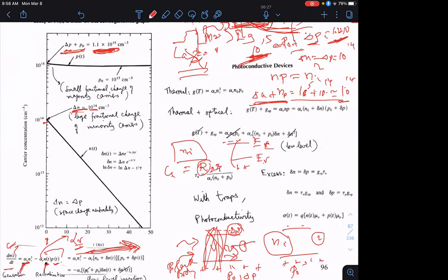It's an unstable scenario. So subsequently, these electrons fall into the hole state, re-emit photons. You absorb more photons, you create more electron hole pairs, they recombine, emit photons, and it's a constant exchange of energy with the surrounding environment, and that is what establishes the intrinsic carrier concentration N sub i.